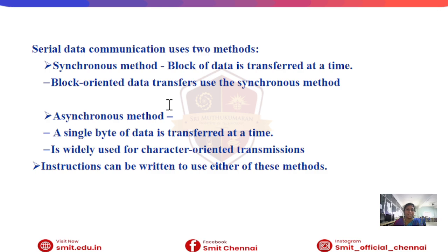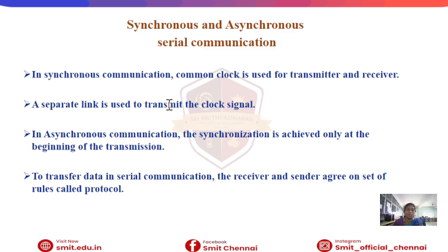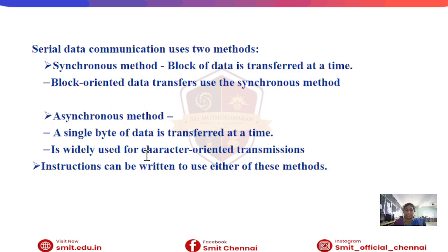The next one is asynchronous communication. No clock signal is needed between the transmitting and receiving stations. The synchronization is achieved using start and stop bits. It is simpler and widely used, for example UART communication. The important point is that the 8051 serial port mainly uses asynchronous communication.